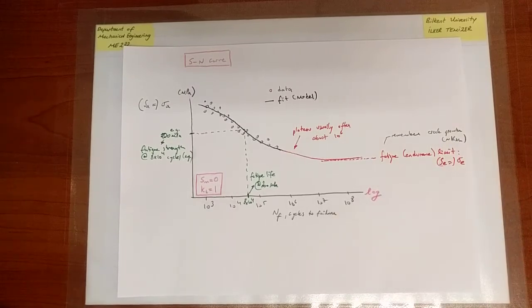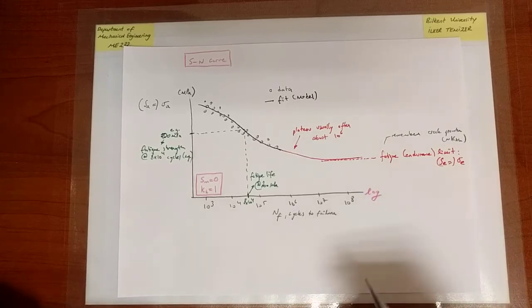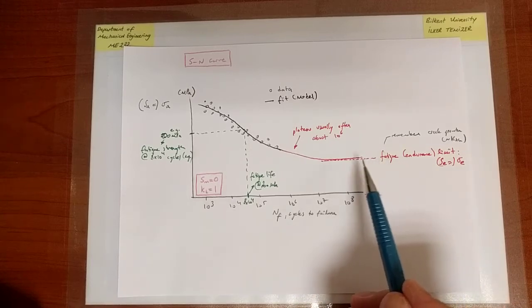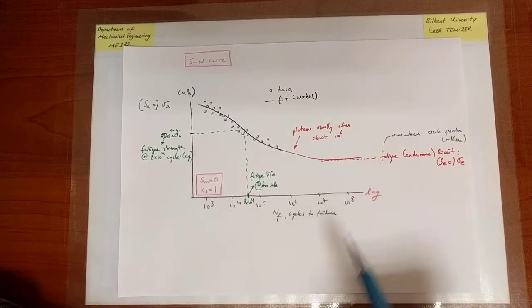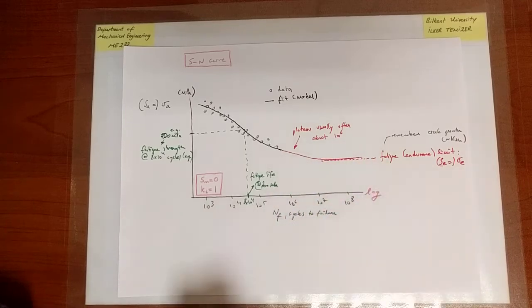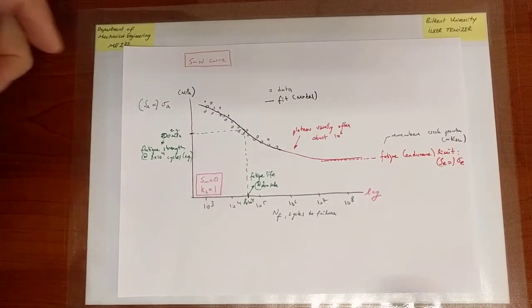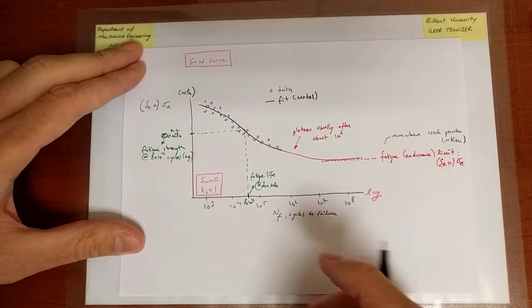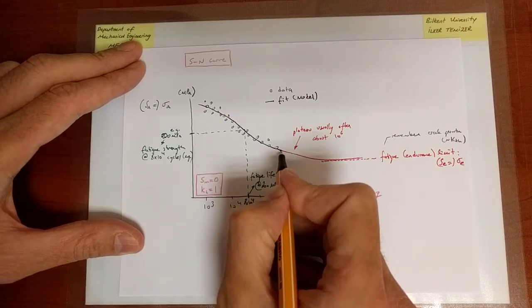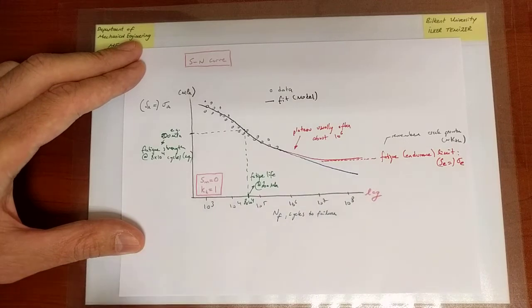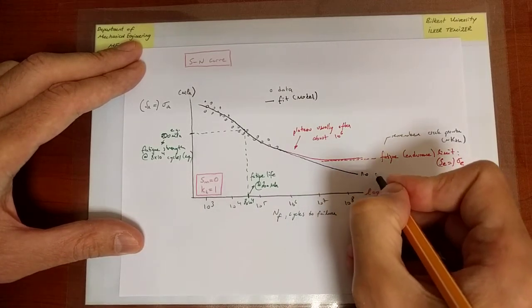There are such materials. Now, because fatigue ultimately has to do with the initiation, growth, and merging of cracks, it turns out that similarly, there is a certain stress amplitude below which the cracks just don't grow enough to cause fatigue in a reasonable number of cycles. So this curve levels off to almost a horizontal appearance. Now, does this always happen? No. Just like you don't always have a threshold value, you don't always have an endurance limit. So sometimes the curve just goes on like this forever.